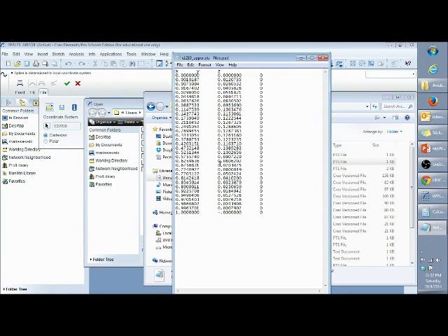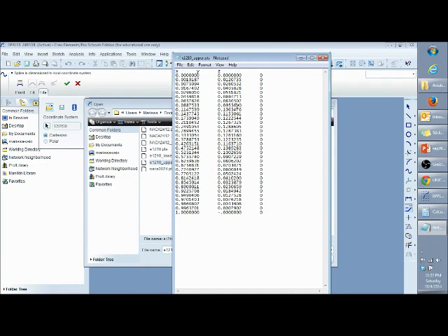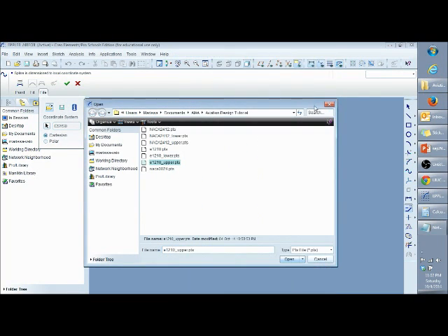Upper. So when you're looking at your file, keep in mind where your origin is, where it starts off, and where it ends. So I drew that first curve correctly. I have come across files that freak out on you if it starts from 1 here and then ends at 0 here. You'll have to draw your line backwards if that's the case for your airfoil, just to keep it from freaking out on you.